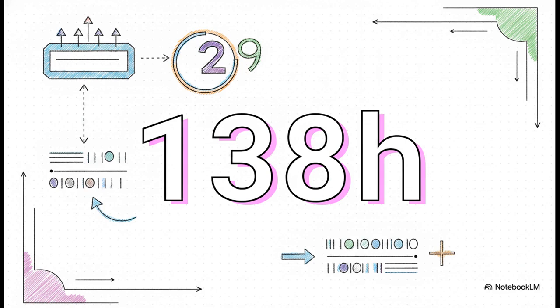To add them safely, we have to align the binary point. We do this by taking the second value and right-shifting it by 1. This essentially divides its scale factor to perfectly match 2 to the 8th. The raw hardware value then becomes 138H. Now, and literally only now, can the integer hardware safely add these two hexadecimal numbers together.